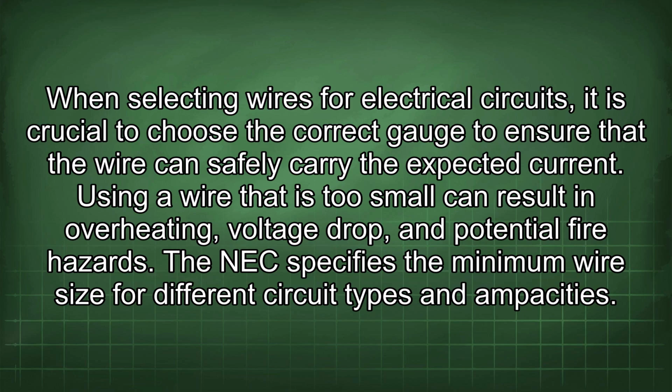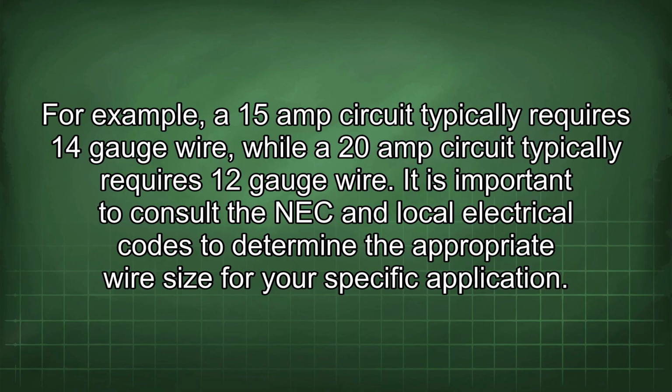Safely carry the expected current. Using a wire that is too small can result in overheating, voltage drop, and potential fire hazards. The NEC specifies the minimum wire size for different circuit types and ampacities. For example, a 15 amp circuit typically requires 14 gauge wire, while a 20 amp circuit typically requires 12 gauge wire. It is important to consult the NEC and local electrical codes to determine the appropriate wire size for your